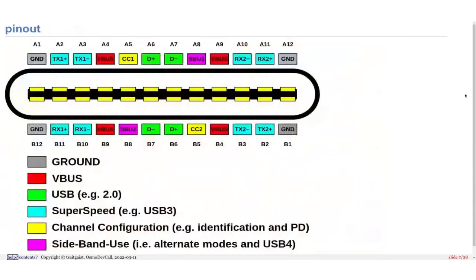So the USB-C connector looks like this in schematic, and you can already see how this can be reversible, because if you have the symmetry point in the center, when you reverse the A side to the B side, almost all connections are the same. You have 4 ground connections on the outer reach.